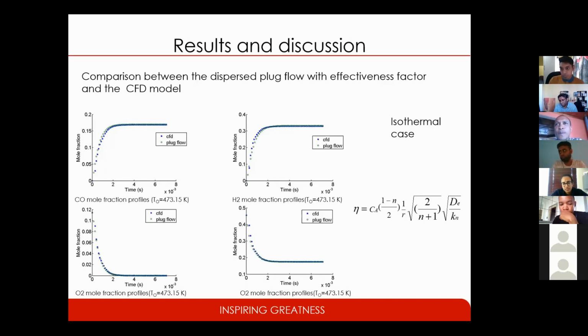Okay. I remember, as I said, you would think of this as a heat transfer problem because you have heat transfer across channels, right? So the analytical equations that were very important in this scale were the heat transfer across the channels. So you have the free flow that I spoke about, which is the heat transfer in the gaseous phase, and you also have heat transfer on the catalytic surface or on the walls, from one channel to the rest. So those are the 2 equations that I combined together.